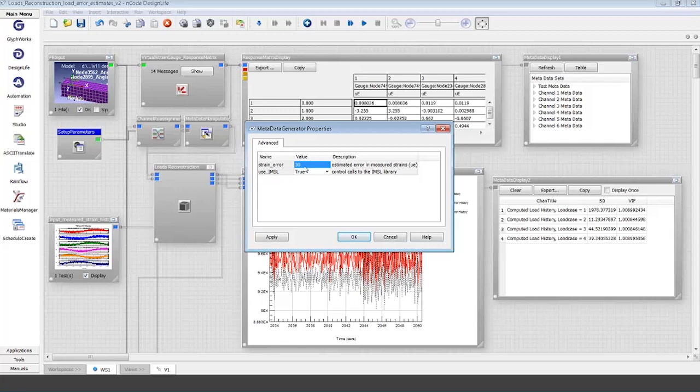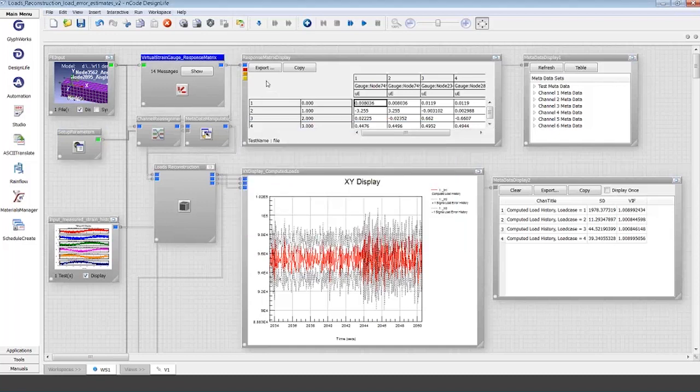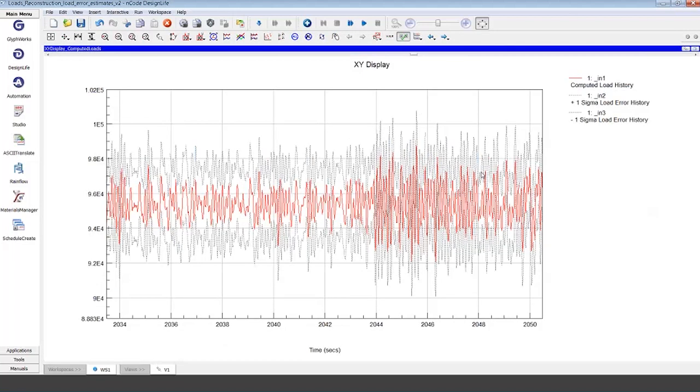You could look at measured strain gauge data when the part is not in use. So when the vehicle's turned on, when the aircraft is sitting on the runway, when the phone is turned on but not being used, what's the squiggliness, you could say, the variability in the strain response, and I can use that here. So now we're introducing a probabilistic side of things, or introducing a variable into the system. And depending on how well conditioned this strain gauge sensitivity matrix is, depending on how precise its capability is to understand degrees of freedom of loading as in strains, that cascades through into making plots like this, where we can quantify this variability. So we have plus or minus 1 sigma being shown here in these ghostly gray lines at the top and the bottom.